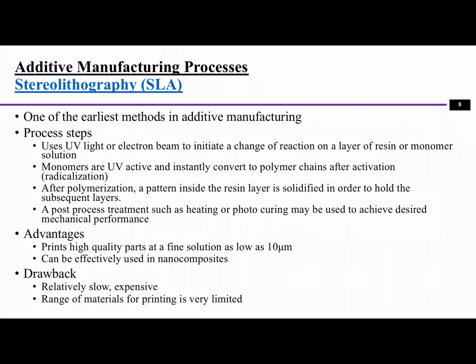It's unlike fused deposition modeling. In fused deposition modeling, you are depositing the materials layer by layer, and then sometimes there are distortions from the heat, thermal expansions of the materials. They can affect the accuracy as well.